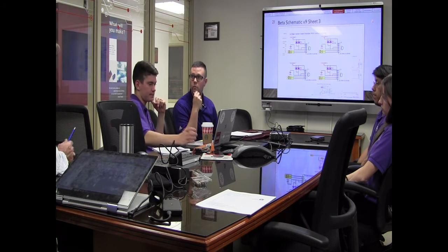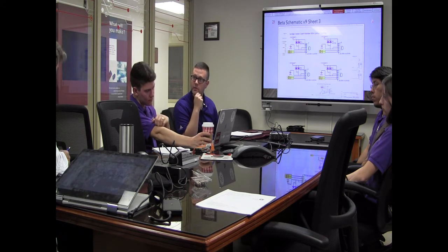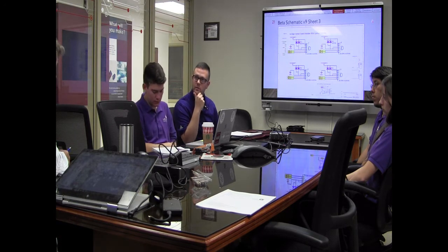And you're sure you were getting 12 volts unloaded at that output? Yeah, it's routed directly across the board from our 12 volt. But did you measure it at that connector when it was unloaded? Yes. And it's 12 volts? Yeah, during testing.